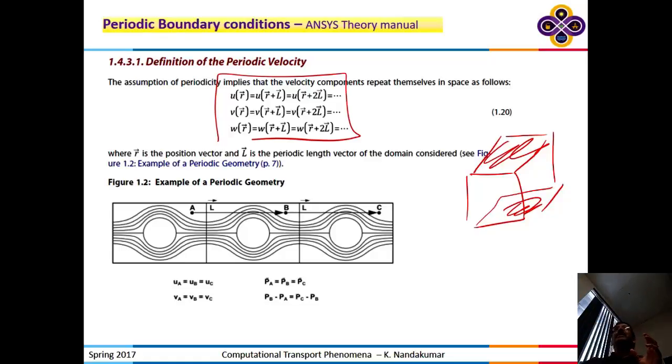So in fact, that was the attempt to see whether you can predict the Kolmogorov energy distribution from direct numerical simulation. And that you can do. Okay, but the starting length scale would be determined by the size of the box that you pick, in subsets perhaps. Okay, but yeah, you can use it. People have used periodic boxes for studying turbulent flows and for studying porous media flows.